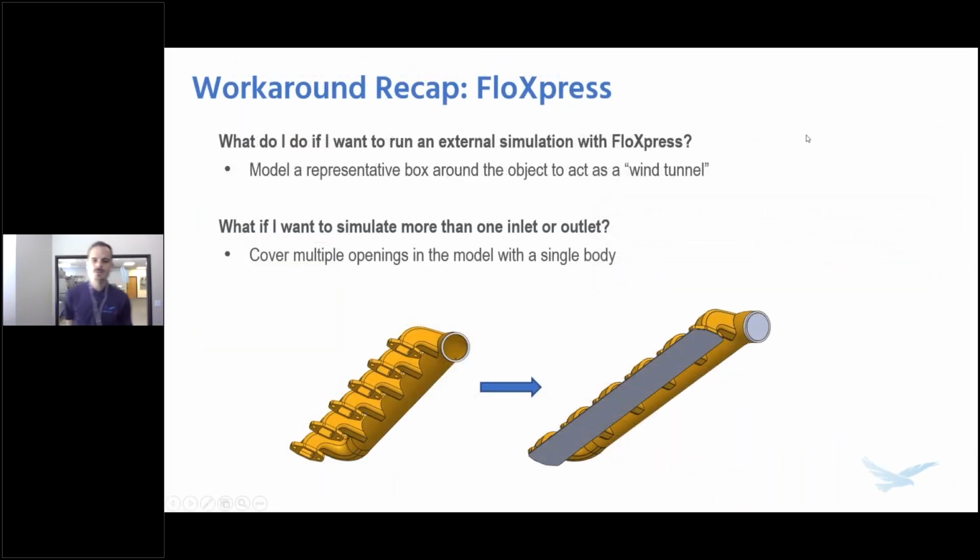So just to recap some of those workarounds, again, we didn't have to do any kind of save as part or combining bodies because FloXpress will work as an assembly, but we did have to save the model out to another copy in order to model a box around that in order to simulate the airflow. So FloXpress is for internal simulations only, so sometimes you have to model some other kind of container to trick it into thinking that the external airspace is internal.